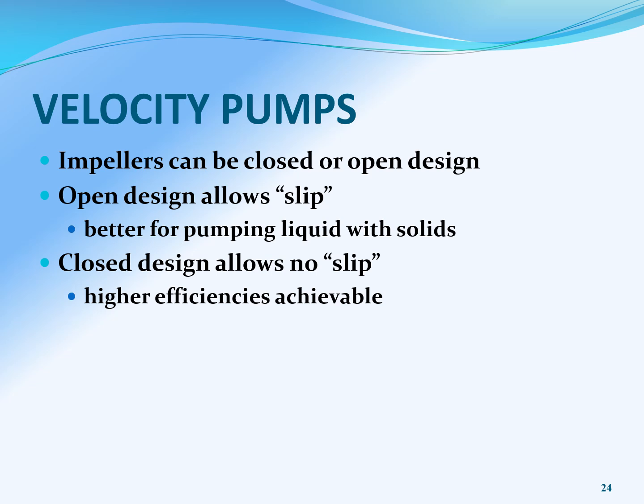A couple of different impeller designs: you can have them open or closed. The open design allows for slip, meaning that you're not pumping with such high efficiency or preciseness, but it is good because you can pump liquids with solids in them. That's why you would want that openness, because it allows for the passage of those solids. But in the closed design, or the no-slip type, you definitely don't want any kind of solids. It is used for pumping at higher efficiencies.